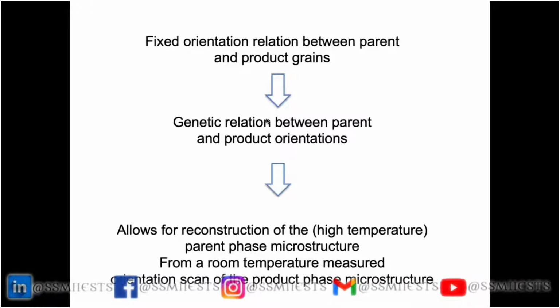By DNA tests, you can determine whether or not person XY is the parent of person Z. In texture we have something similar. We can use those crystallographic correspondences to check, if you have 2 grains in a product texture, whether or not they have a common austenite parent.